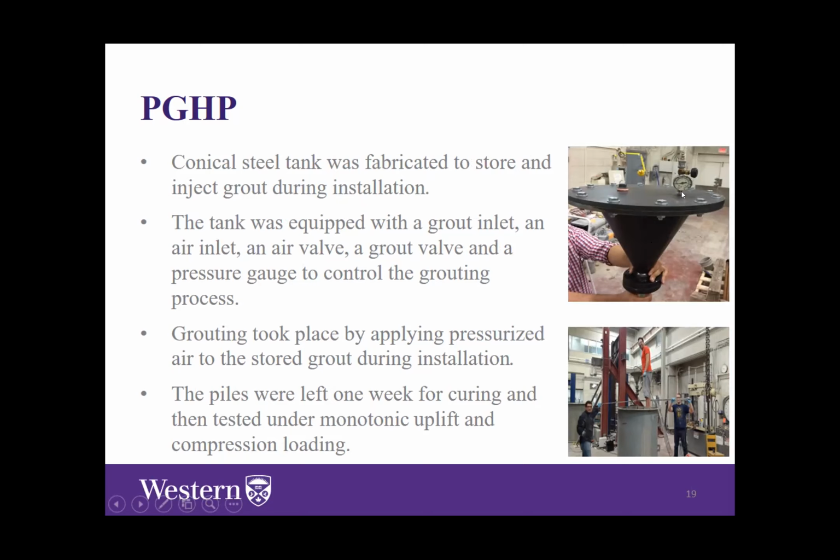We have a grout valve to control the grouting process, closing and opening, and a pressure gauge here also to monitor the injection grout pressure. So the grouting took place by applying air pressure to the stored grout, and then the grout is pushed through the hollow helical pile shaft and through the grout nozzles into the surrounding soil.